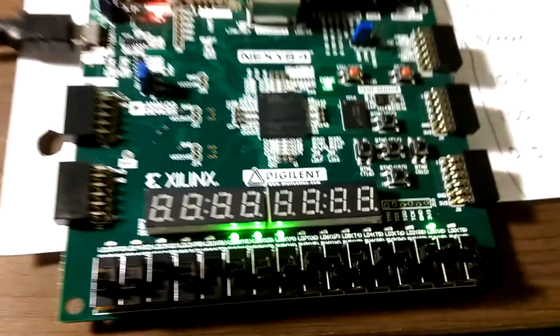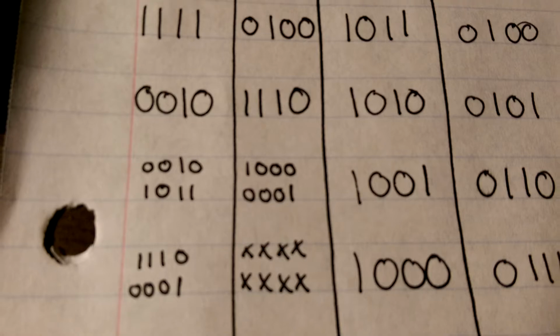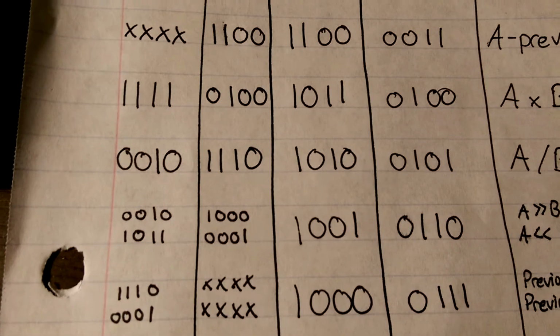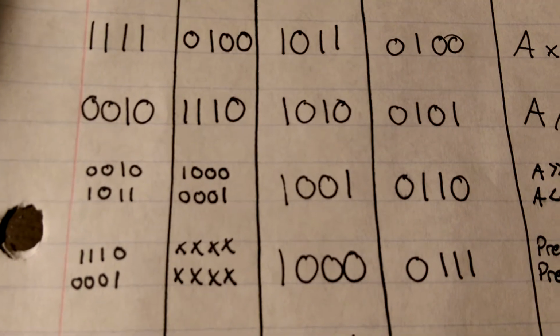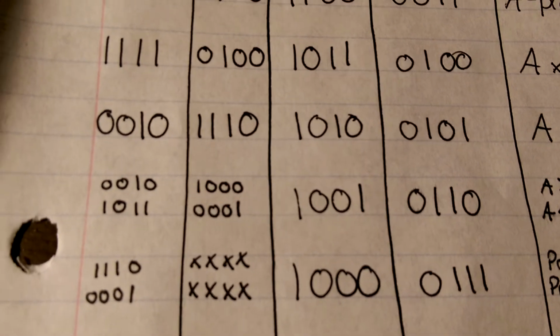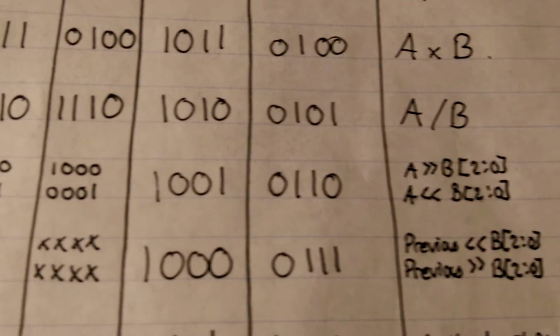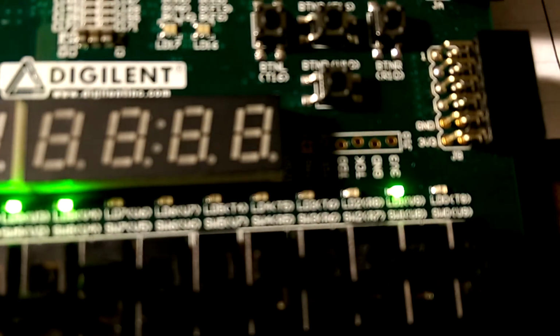And yes, A was shifted right by 2 bits. This is the output you see. So you have your 8. Well, the most significant bit, the 4th position, moved by 2, should now be in the 2nd position. This is what we see as the output. Right? So now let's save that.